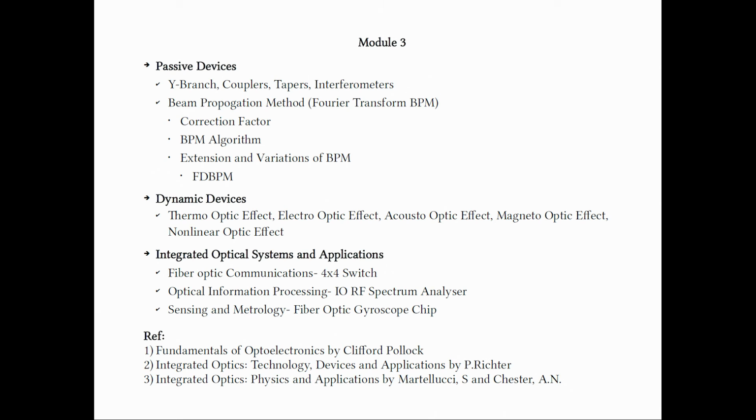So, then we looked at some optical systems of application of all these devices that we have studied, and also some applications. In particular we have looked at an example of a fiber optic communication system where we can make a 4x4 optical switch by using 5 directional coupler switches. By configuring these directional coupler switches, we can get many connectivity